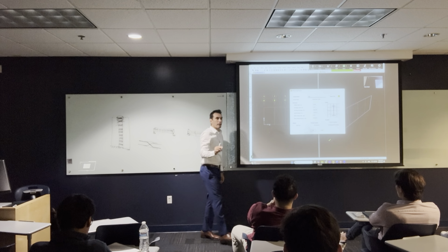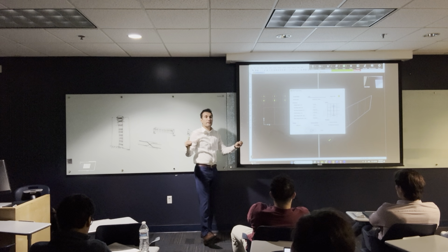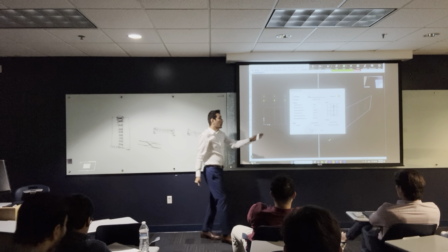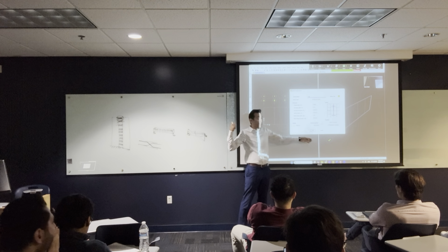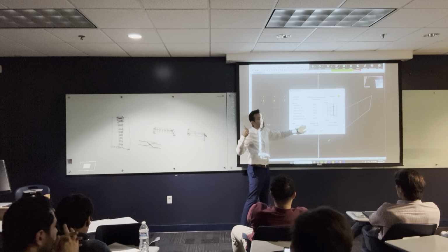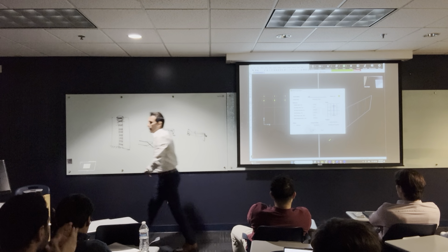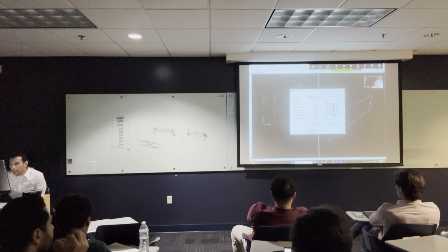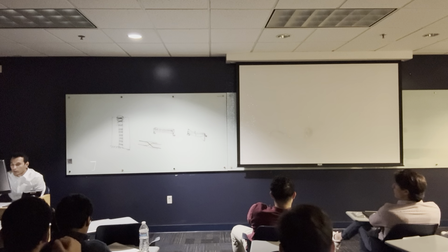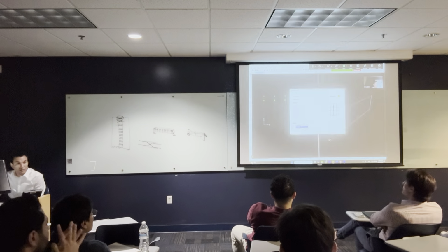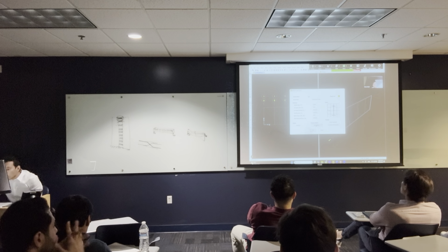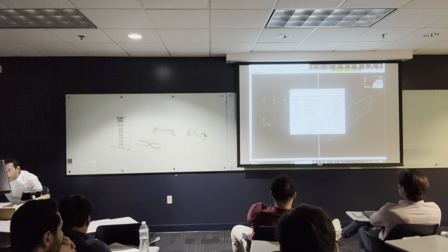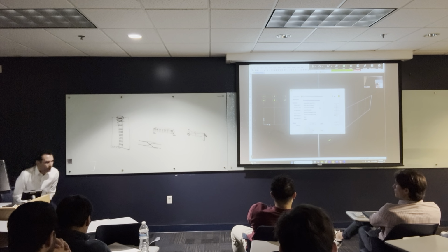Let's say that you are going to use different materials for the different steel sections that you have. So here, all the materials that you have are going to show up here. If you define 10 materials, once you click on this one, you are going to see all the materials that you have. So I'm going to click here, and basically SAP 2000 knows that this is a steel cross section, so it assigned the steel material to this section. Okay? There's something here, it's called set modifiers. I'm going to talk about these modifiers.